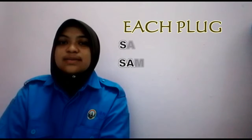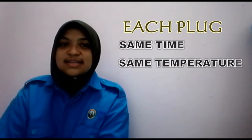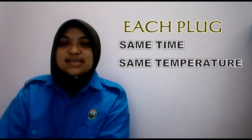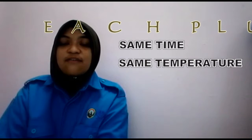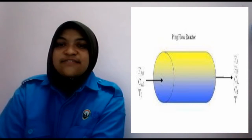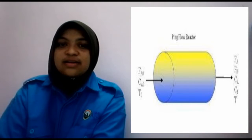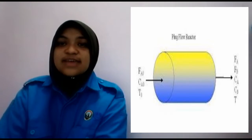Plug flow condition means that all the material processed through the reactor must have the same residence time, so that the chemicals exiting the reactor have witnessed the same reaction conditions: reactive species, contact time, aging, and temperature history. As you see from the picture, the molar flow rate at the inlet and the outlet is different because the reactant has reacted.